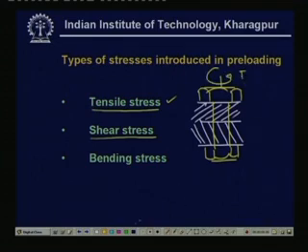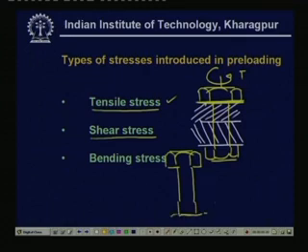So if you consider this surface, then there will be some frictional force acting, and that will cause the frictional torque. If you draw the free body diagram of the bolt, then it looks like this. So this part here, what we see is the frictional torque acting.